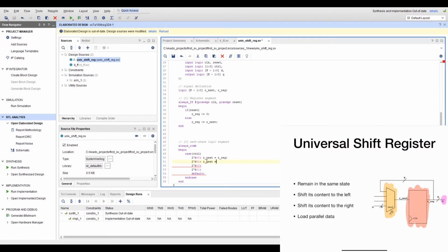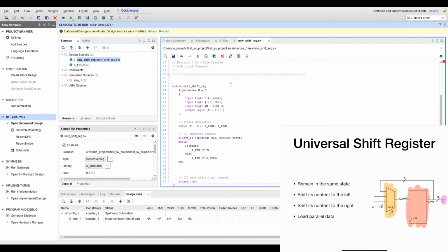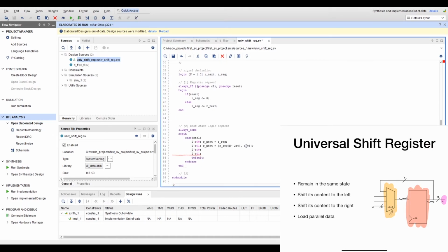These are the serial in and serial out, and I'm just going to use a concatenation. It's just easier to write, and you can read it on your own. It's not really difficult. I'll explain it briefly: here I'm concatenating. I will be using the least significant bit of D, which is 8-bit, for example, or n-bit depending on how much we have. I will stick it to the least significant bit, and then keep the n minus 1 upper bits here. I'm just concatenating them. And if you think about it, this is a shift to the left side. So I'm pushing everything to the left side.